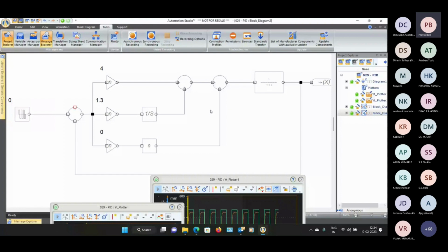That is the hardware interface. The third one is if you want to work at API level. Serious users in the industry, a lot of them have bought the Automation Studio API, especially a defense organization in Pune. They do a co-simulation with Simulation X or with Simulink. Then they take that Simulink model, generate the target code and burn it on a DSP board, which will do the control in the real world.